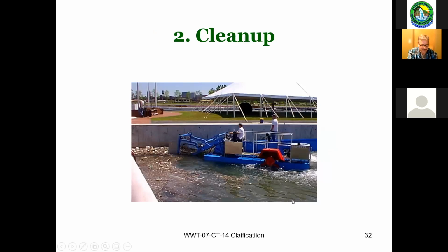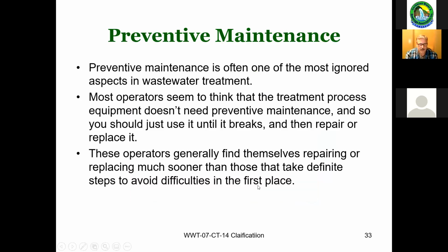Clean up. This is obviously a very big tank, but they need to be cleaned. On the smaller tanks, you want to do your scum removal at least once a day and your inspection at least once a day. I'm not sure of the size of your facilities and whether you have millwrights or mechanical staff, but most operation staff are required to do some kind of preventative maintenance, whether it be greasing or just general inspection. Maybe even shear pins need to be replaced.